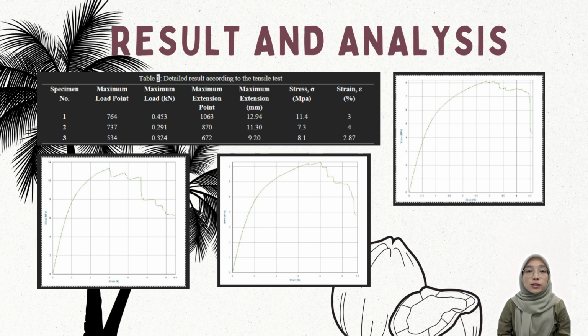Then, plate 3 shows a moderate tensile strength and load-bearing capacity because of changes or inconsistency in variations such as less curing time in the manufacturing process, which could lead to a decrease in tensile strength and the ability to withstand greater load. As a result, the manufacturing process from plate 1 should be chosen as the benchmark for other testing.